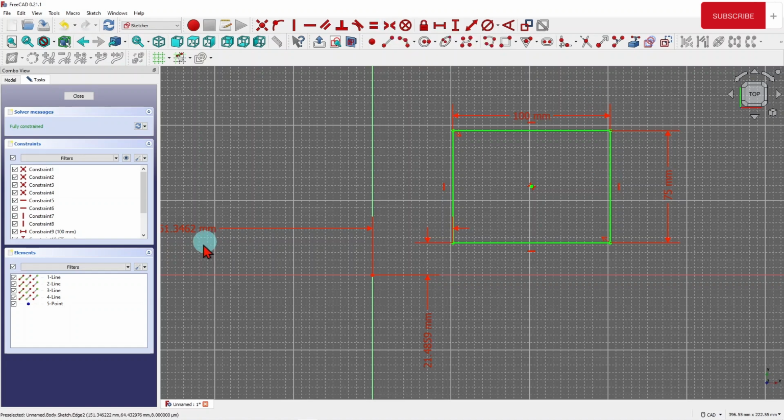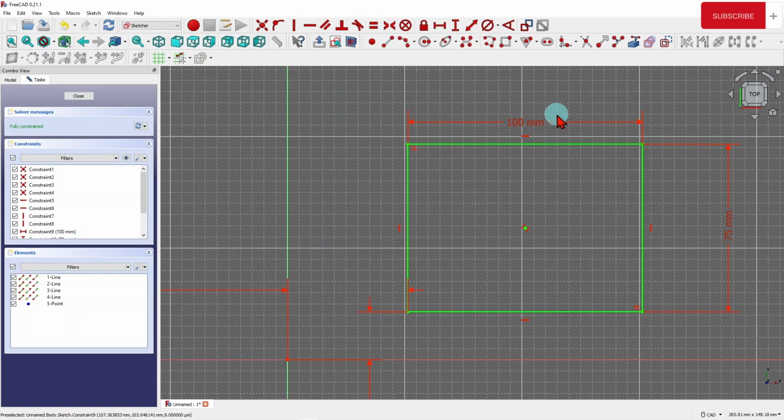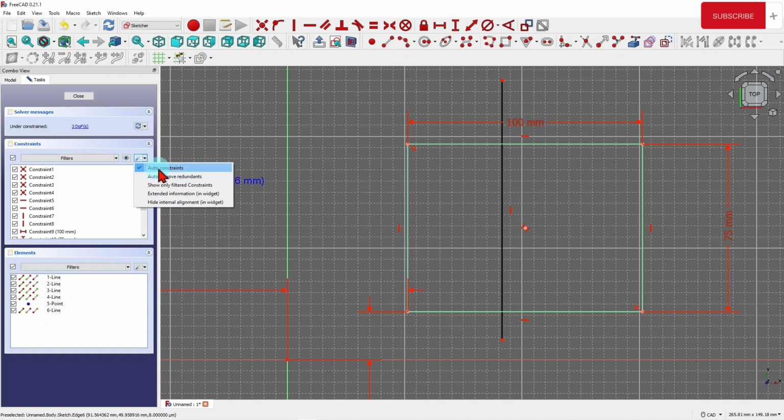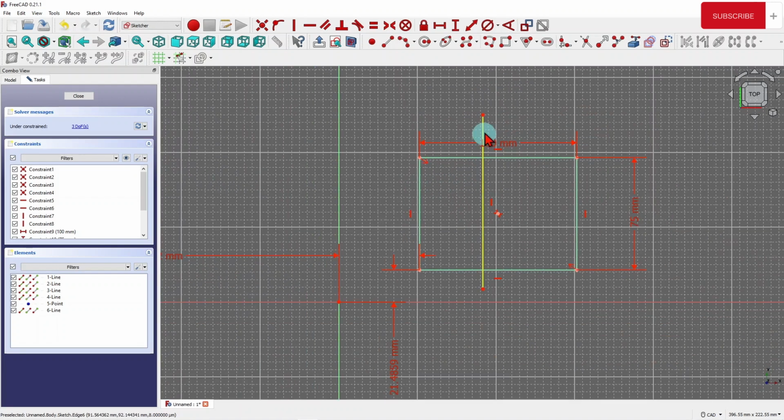Okay. Now, once we have done that, we're going to put some more construction lines on this. So I'm going to arbitrarily create some lines. Since I have the auto constraining feature, whenever I draw something, if it is closer to being vertical, it'll automatically put a vertical constraint, right? And then I will do another one like this, and it is now horizontal. Right click, get out of here.